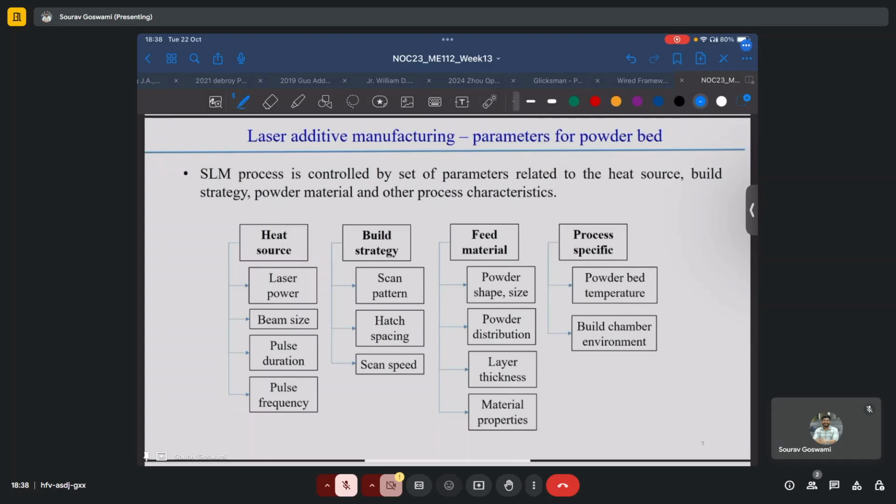In terms of size, while we do aim to keep powders of a predetermined, say, mean size, we do know that it is impossible to obtain powder particles of only one size. Rather, we always have a distribution. The distribution can be tightly controlled, so it can be a small distribution compared to a wider distribution, but that will drive up the costs.